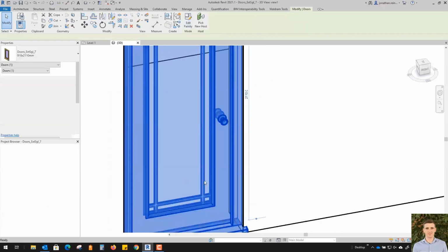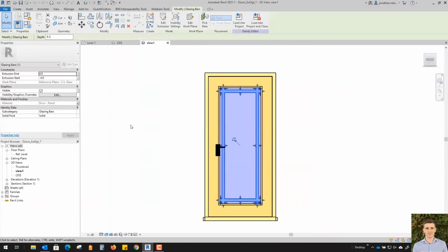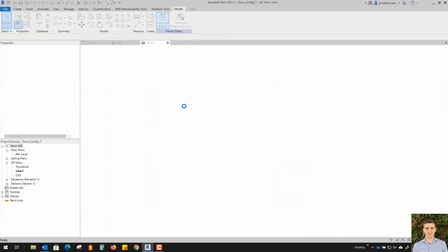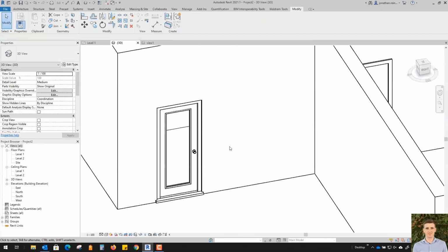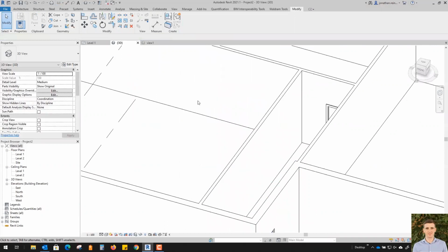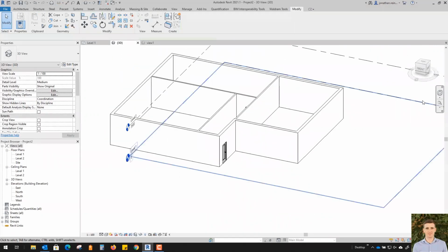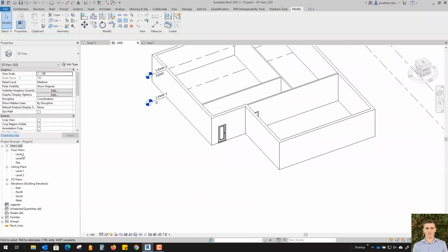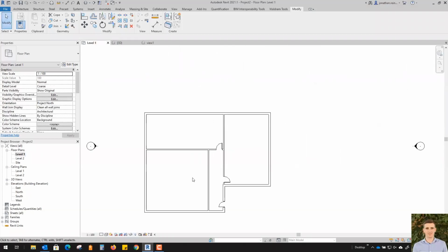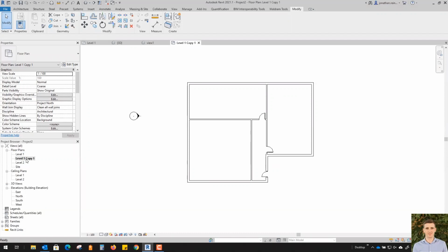One example of editing a Revit family that comes installed with Revit itself already is one of these doors, for example. I like using this door, but I don't like the internal trim that comes on the glazing. It just, for my particular style of architecture, I don't feel it's very contemporary. So I can simply just go into that family, edit family, and just delete those elements within that particular family and load it back into the project. So it's good to use that Revit object as a basis for your design and your modeling objects as well.